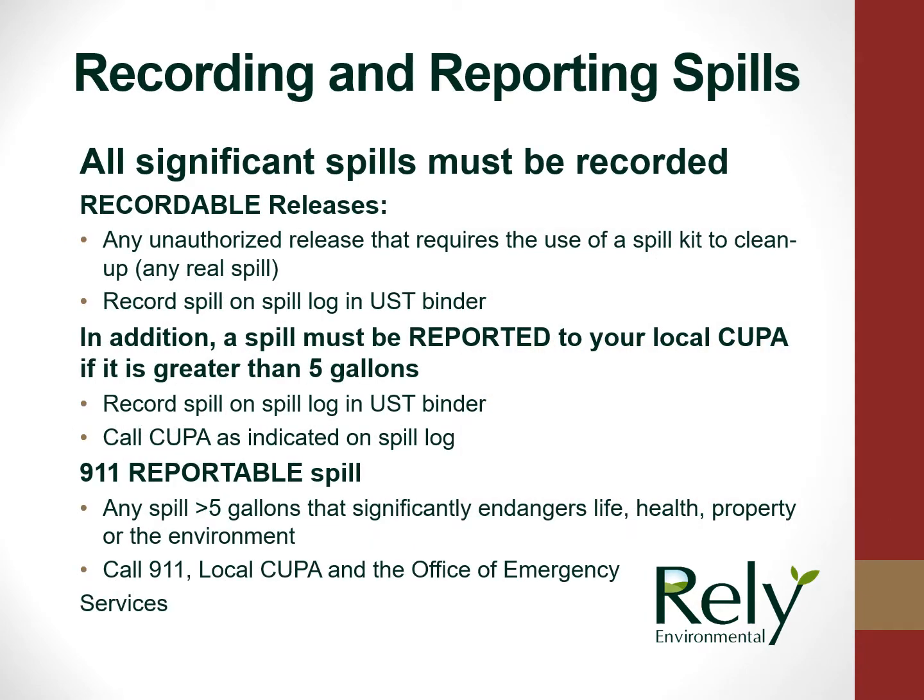All significant spills must be recorded. A recordable release is any unauthorized release that requires the use of a spill kit to clean. These spills must be recorded in the spill log. In addition, a spill must be reported to your local CUPA if it is greater than 5 gallons. A 911 reportable spill is any spill greater than 5 gallons that significantly endangers life, health, property, or the environment. In the event of a spill such as this, you must call 911, the local CUPA, and the Office of Emergency Services.